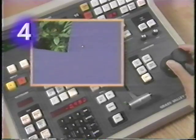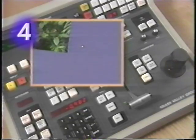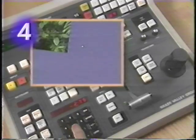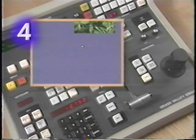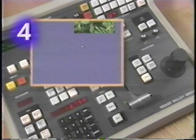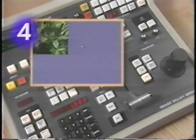To enter an orbit value, select Z. For this example, enter minus 2.75 and press Enter. The picture will orbit counterclockwise 2 3/4 times. Orbits are not visible when you enter them with the keypad. You only see the ending position of the picture.